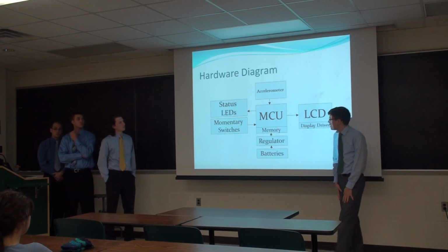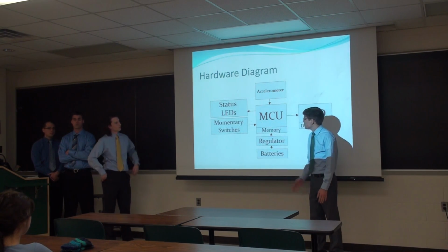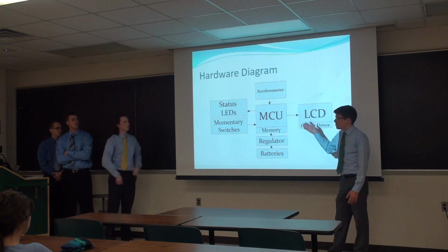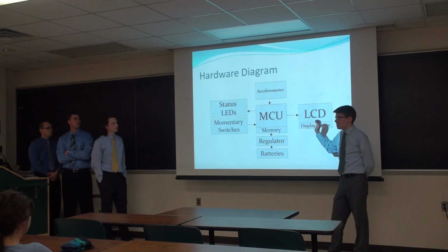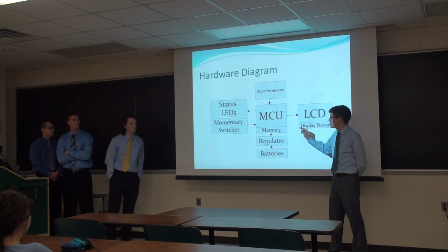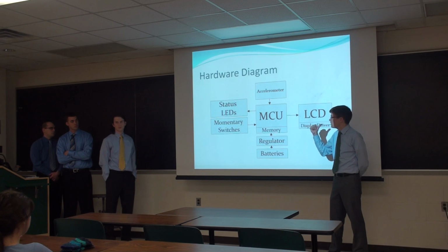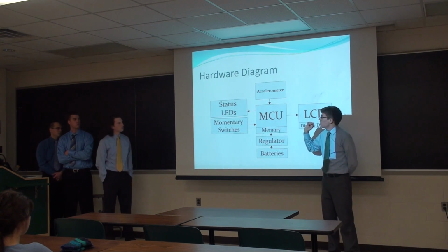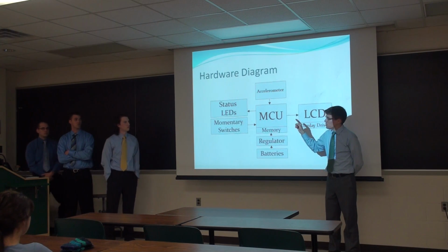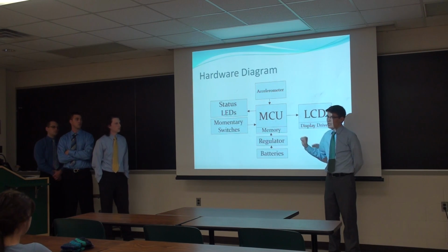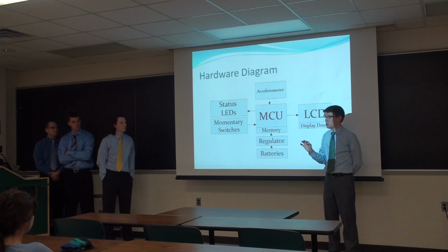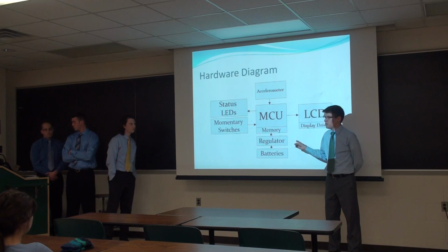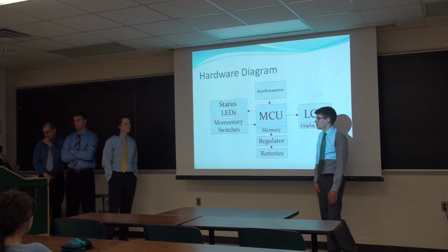As you can see, at the heart of our device, we have a microcontroller. It receives data from an accelerometer. It does a lot of internal processing in software, and when it's in the peak hold mode, it stores values in its own memory. And then it outputs those values to the LCD through a Hitachi display driver. It also uses LEDs for status, and it uses momentary switches to take in input about scrolling on the screen and setting the mode and setting the time. It runs off 2 AA batteries, and we're using a 5-volt DC to DC step-up.